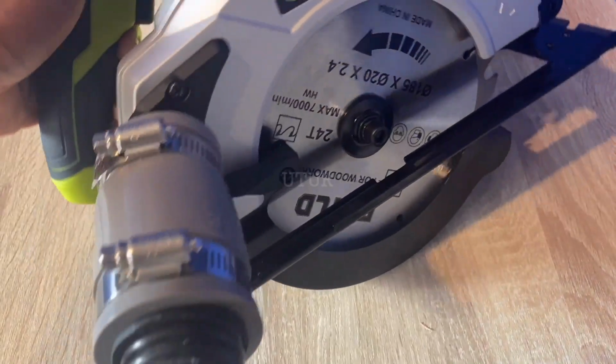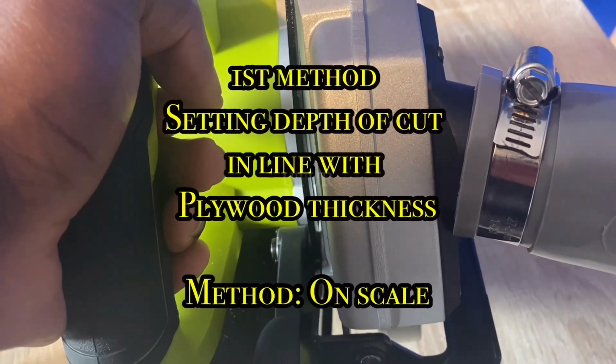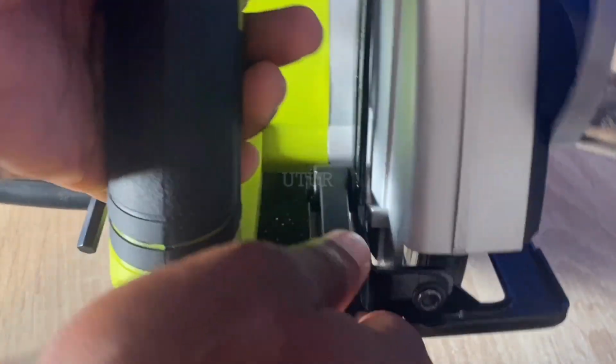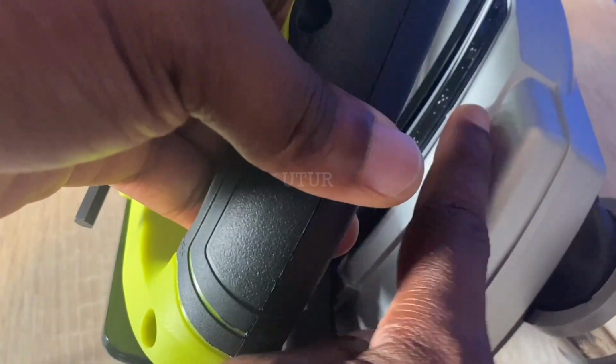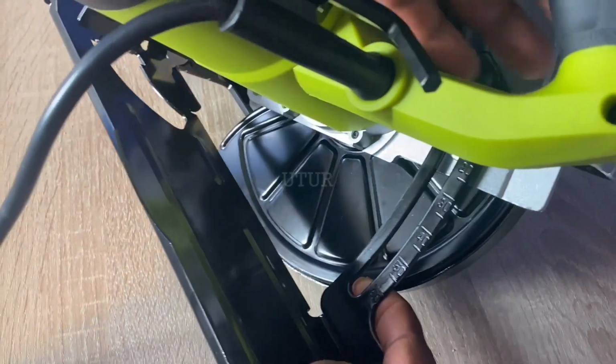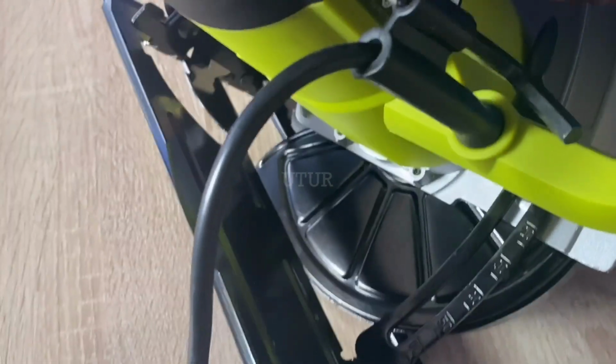To reduce the depth of cut to 12mm or 15mm, we lift the depth of cut lock lever and raise the saw body away from the base plate. And straight away on visual inspection, we can see that the depth of cut scale's limit is up to 65mm. Okay, that's the upper threshold value range.